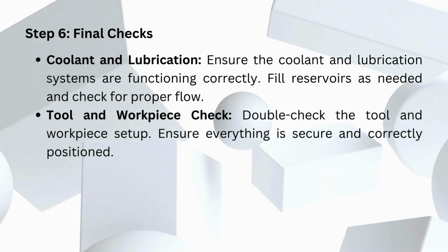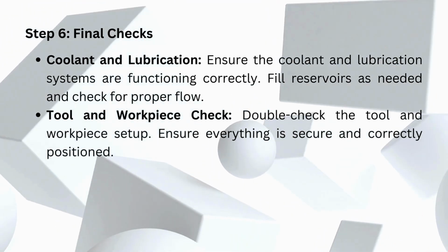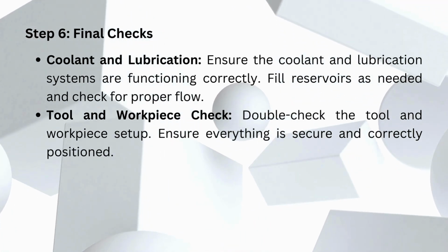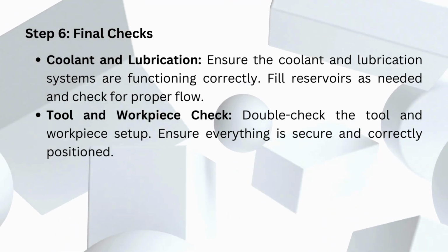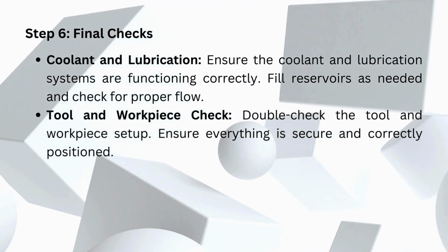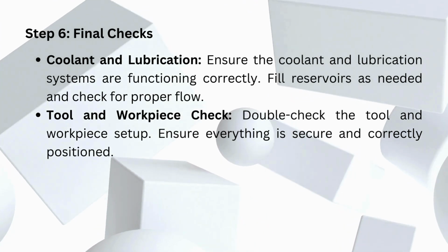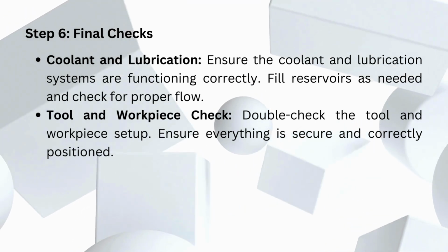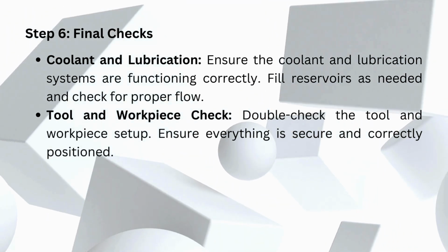Step 6. Final checks. Coolant and lubrication. Ensure the coolant and lubrication systems are functioning correctly. Fill reservoirs as needed and check for proper flow. Tool and workpiece check. Double-check the tool and workpiece setup. Ensure everything is secure and correctly positioned.